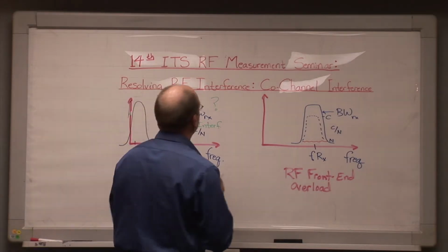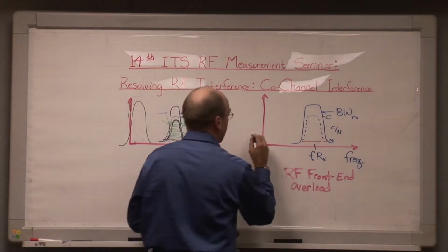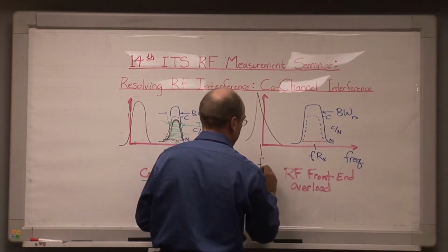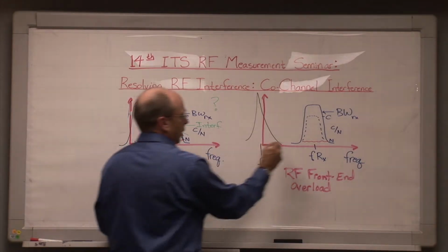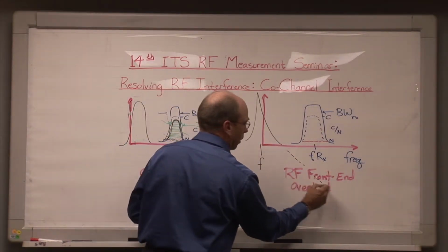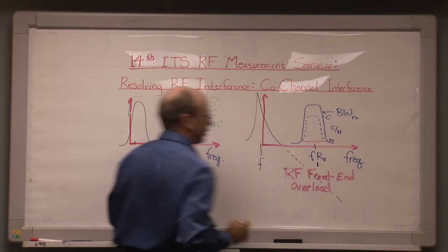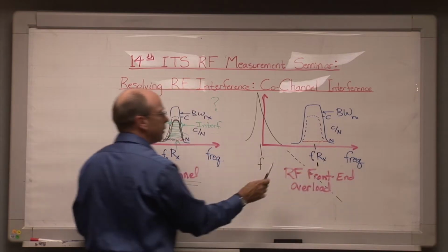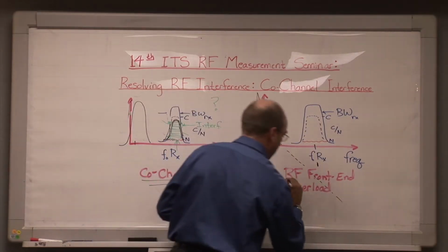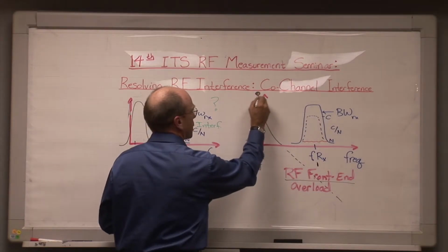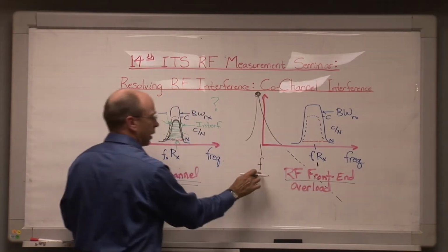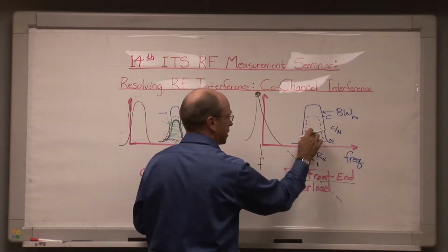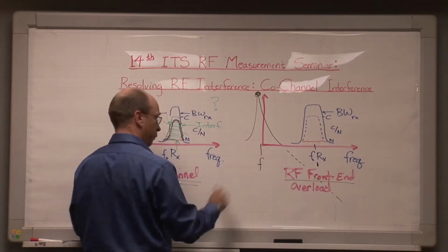What we'll talk about for the second talk on RF front-end overload is a case where an emitter is putting out energy over here on some particular frequency, and no measurable energy at all is being produced over here on the frequency of the receiver that is having a problem, but due to the behavior of the RF front end of this receiver, this energy at the desired frequency of the transmitter that's causing the problem, in fact, will cause this system to degrade in performance.